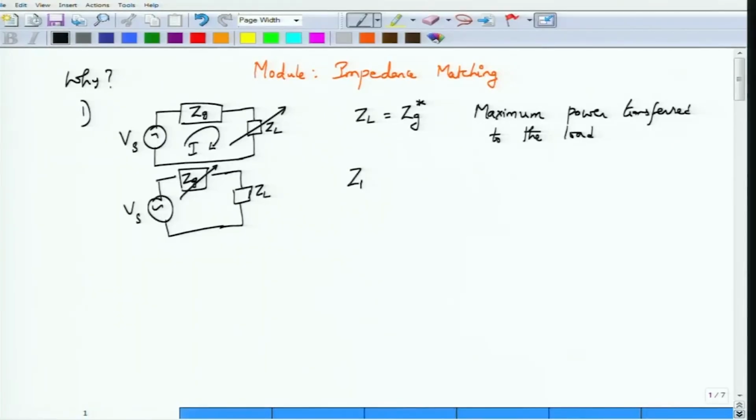Most people would say that, well, maximum power transfer cannot be wrong because ZL equal to Zg complex conjugate is supposed to give you the maximum power, but they would actually be wrong. Maximum power transfer assumes that Zg is non-zero and it is fixed, and it is ZL which is being varied. If hypothetically I am able to choose the source with an internal impedance, I would actually set Zg equal to 0.